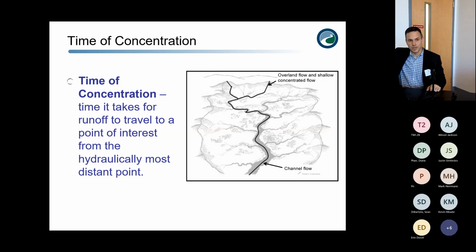We're probably going to go through there pretty quick, all of us at once. If this was a huge auditorium, same runoff volume, but some of us are very far away, it's going to be a trickle out the door, right? If someone from here leaves and someone farther away. So for that same runoff volume, as the time of concentration increases, that's a dramatic decrease in the peak flows that are occurring at that watershed.